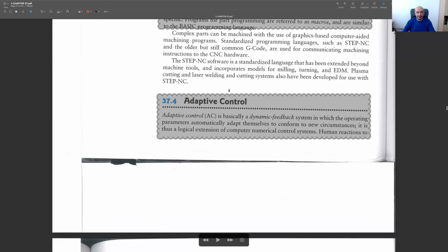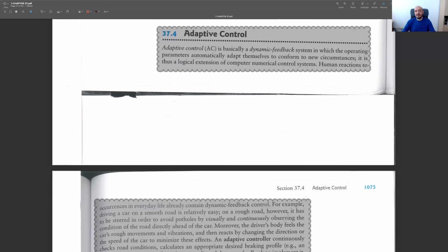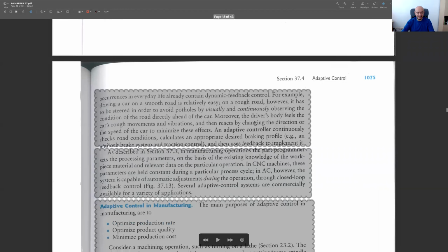And the last topic in terms of control is adaptive control. In adaptive control, we have some intelligence in our control system. In the closed control systems, yes, we have some sensors, but we were only doing some subtraction operation between the desired point and the actual point. But this time, in adaptive control, our comparator, not actually comparator, but the computer will check various inputs, various sensors, and then decide according to the current situation. So in this one, we have more intelligence.